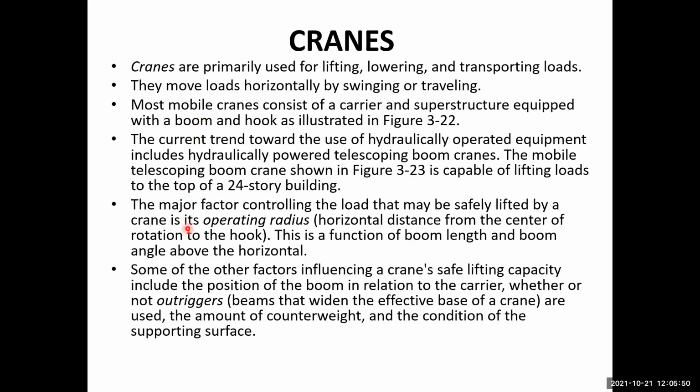The major factor controlling the load that may be safely lifted by a crane is operating radius. So when using the crane, it is a very important characteristic that the load to be lifted should be estimated well. So the load to be lifted by the crane depends on the operating radius of the crane.